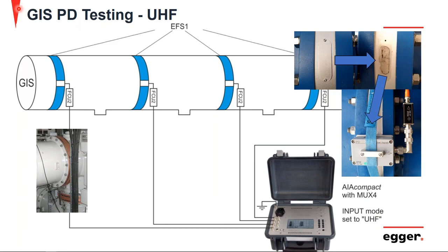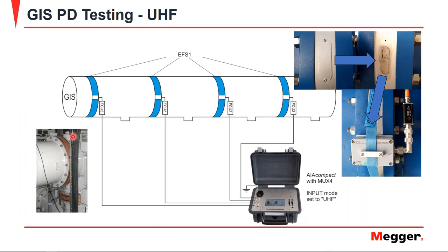Another example would be using the external flange sensors that we had previously discussed, where you can see an external flange sensor here on the flange itself with epoxy, but you may not always have the ability to have that. For instance, if we look at the image here, this is a metallic surface. This is not the epoxy surface, but several of these have these nameplate covers, and often if you remove this nameplate cover, you can see the filling of epoxy underneath it. So if you were to simply add your external flange sensor here, then you can decouple through that epoxy there.